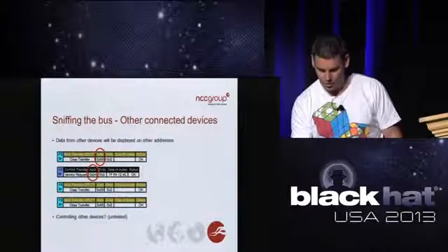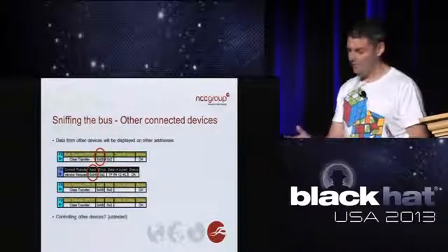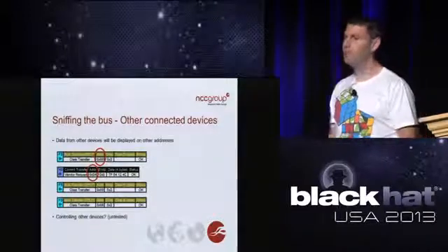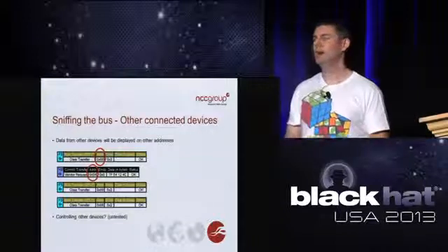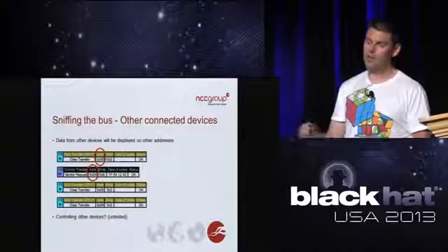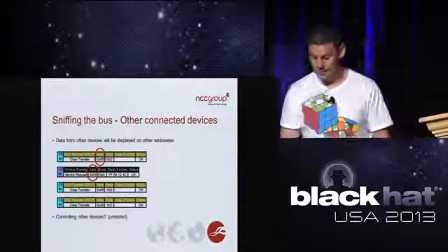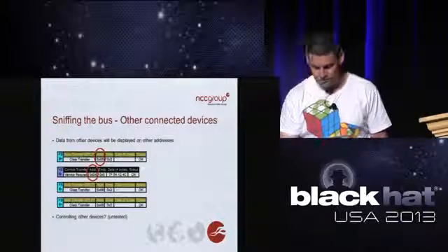And an idea that I've got, as well as information that you could glean purely by sniffing the traffic, because the Facedancer board allows you to emulate a USB host as well as a USB device, potentially you could start requesting descriptors from other devices and gain information about those internally.